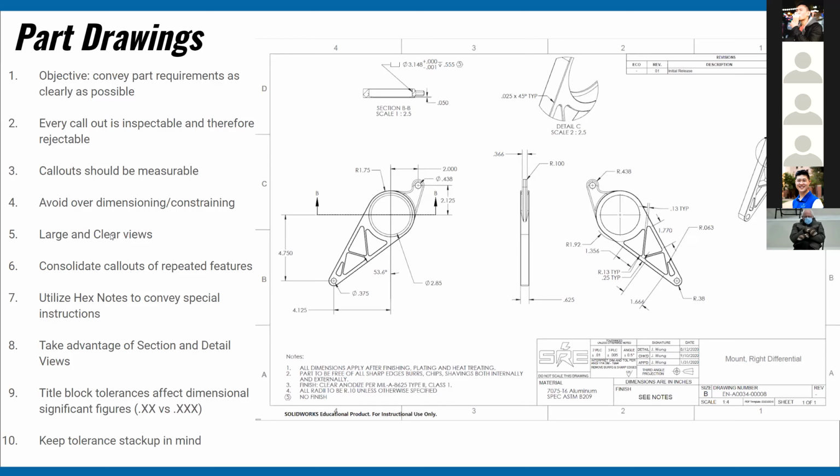No, so you should understand what the requirements of your part are. Like, what is its function? That's what ultimately drives the tolerances on your part. So if you have some non-consequential feature, say a clearance hole that you just need to put a simple rod through, it's not high tolerance, it's not a bearing fit or anything. You can use a two-place dimension.